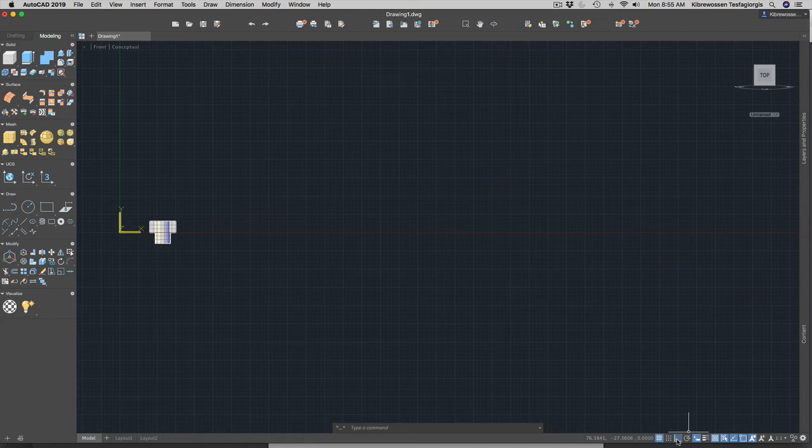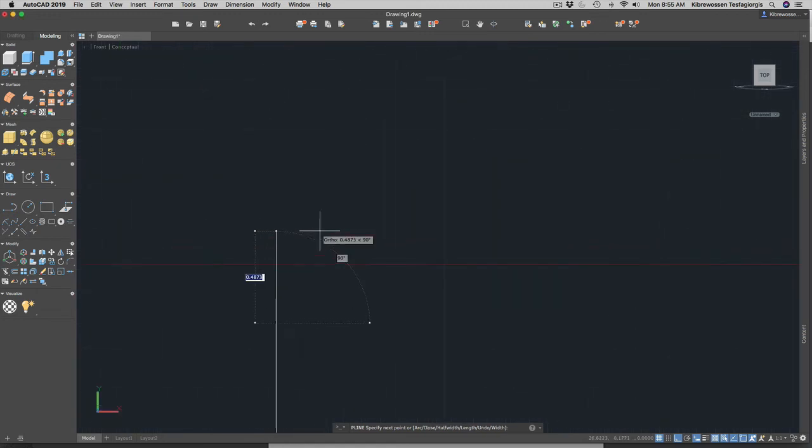Then I'm going to go ahead and start drawing it. Okay, so I'm just starting the polyline function. This is going to be my starting point. Then I'm going to draw it clockwise. Okay, so in this direction it says 1.5. How do I know this? I already figured it out on a paper. So 1 in this direction, then 1.13 down.